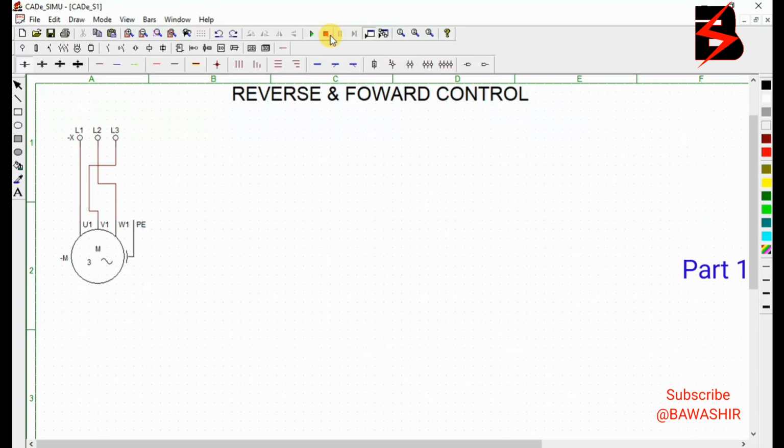This logic is not that you only have to change line 2 and line 3, no. But for a 3-phase motor, when you interchange any two lines, then it's going to change the direction. When it was running clockwise and you interchange, it is going to go anti-clockwise.